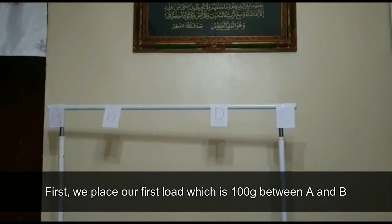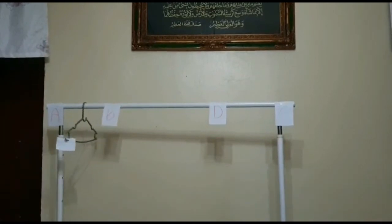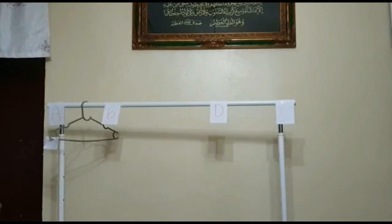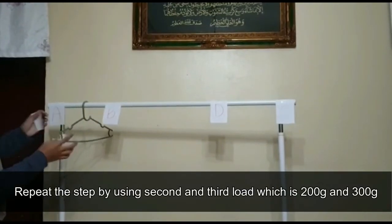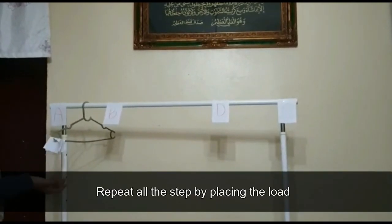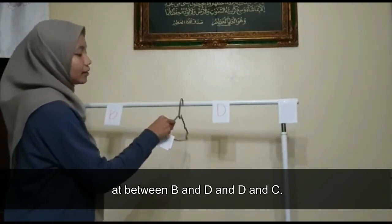First, we place our first load, which is 100 grams, between A and B. The shear force at section XX was measured. Repeat the step by using the second and third loads, which are 200 grams and 300 grams. Repeat all the steps by placing the load between B and D and between D and C.